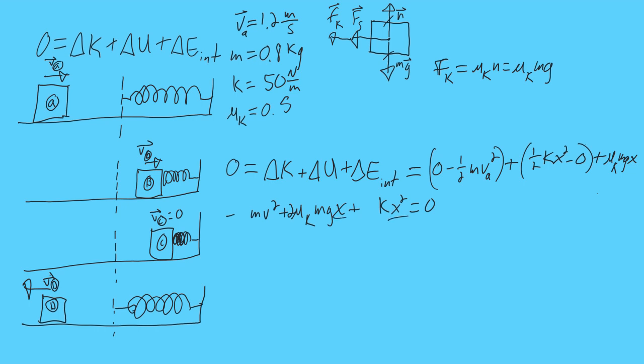We want to find out how much the spring has been compressed. So that's when it gets a little bit ugly, but you should get 2 answers, right? When you plug this into the quadratic formula, you'll get 0.092, and you'll get negative 0.25. Both are in meters. And since we are choosing this to be the positive direction, then we will be compressing it by 0.092.